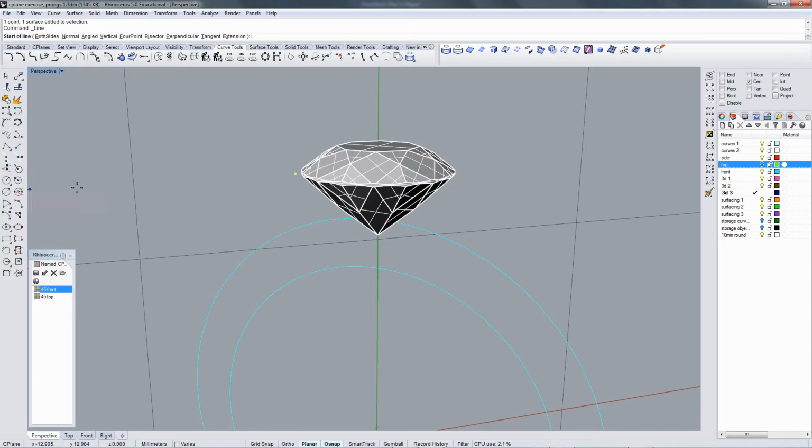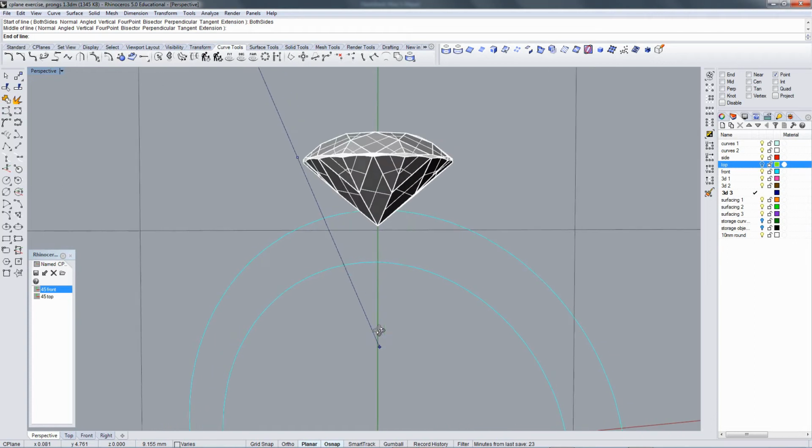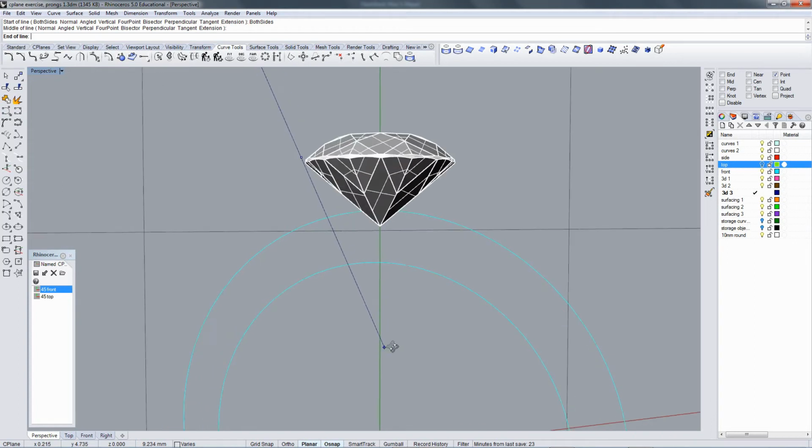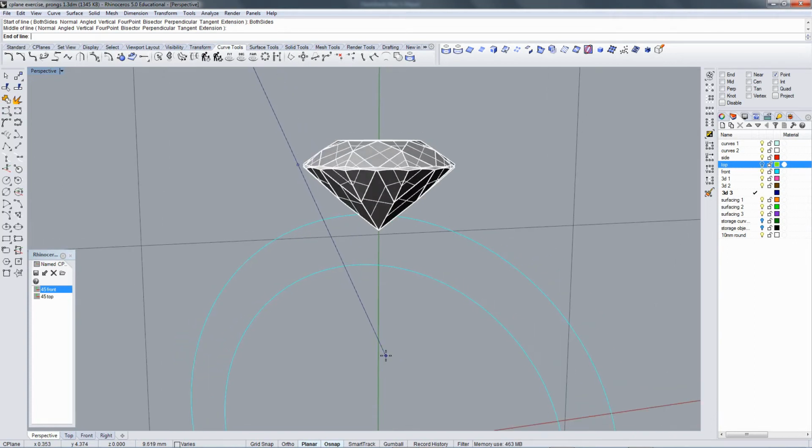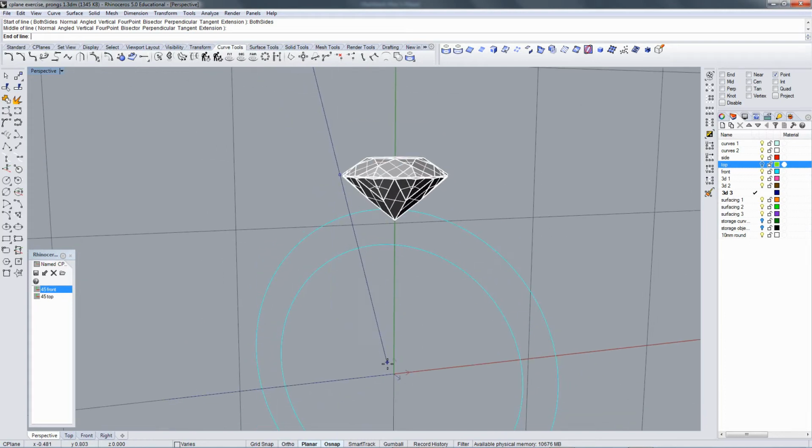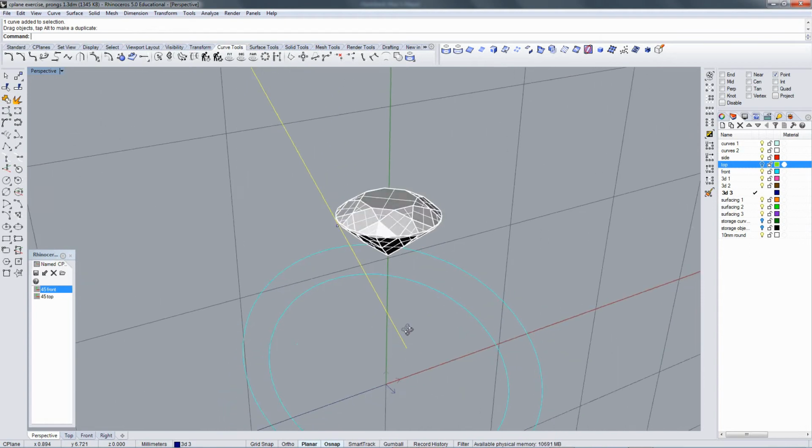To draw that curve, I'm going to draw a line both sides from that point. I want it to flow, fairly a good taper. In commercial jewelry, they'll often have this come down to the center of the ring bore. I find that to be not a very attractive angle. I like to snug it in more. Something like that is fine. Make sure the end of your line drops well below the ring bore.